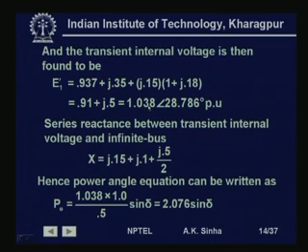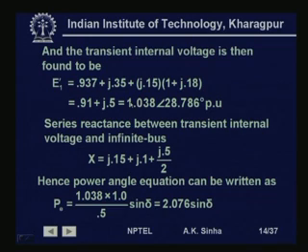Now, for the purpose of the stability analysis, as we had assumed earlier, the voltage behind the transient reactance remains constant, which means the magnitude value remains constant. This assumption we make because we are considering that the automatic voltage regulator is quite slow. It is not able to change the voltage behind the transient reactance in that time. That is, the action of AVR is not taken into account in this case. Otherwise, with the fault, this voltage will increase considerably, because AVR will try to boost the internal voltage considerably by increasing the excitation current.